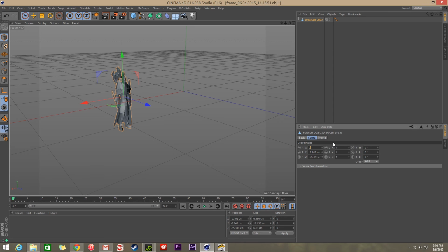So we're going to press 0 once. We have a 0. I'm going to press tab, and we're going to go down one level, and press 0 again, tab, 0. And then we're going to hit enter on that last one, and he'll pop right to the middle. This is his global position we just punched in.